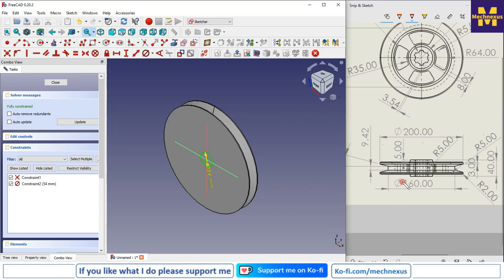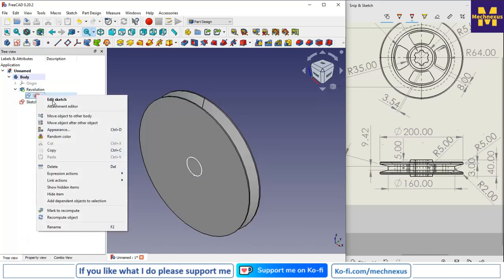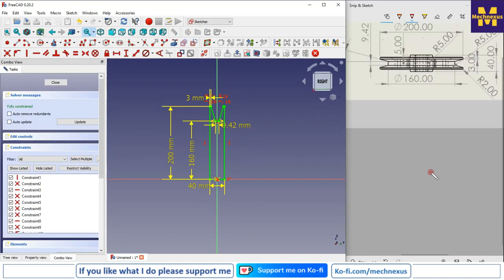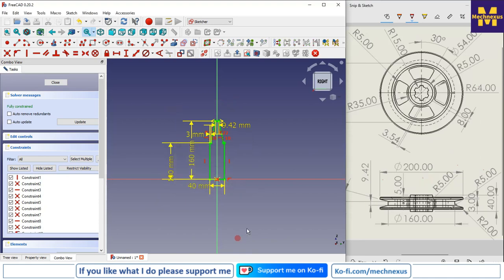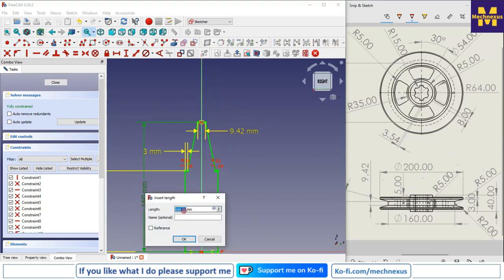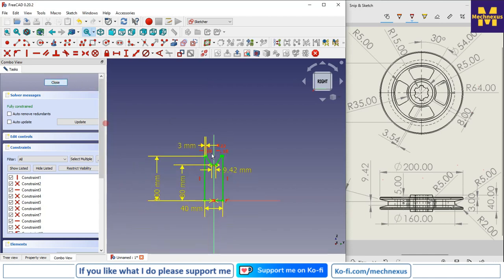So here I think this revolve feature is looking bigger as compared to this diameter, so we will first correct it. So the diameter is 200. So this is the radius, so this is 100, and this is the 160 divided by 2, because this is also a radius, so divide by 2. Now I will close it,